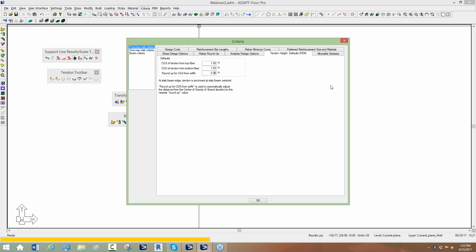But also, if you're in the typical construction of a multi-story sequence, you may run into a condition where the upper floors are actually built prior to the tendons being stressed, and that really only applies to the initial condition where you're stressing the cables and you have to check the stress at what we call the initial or the transfer condition.